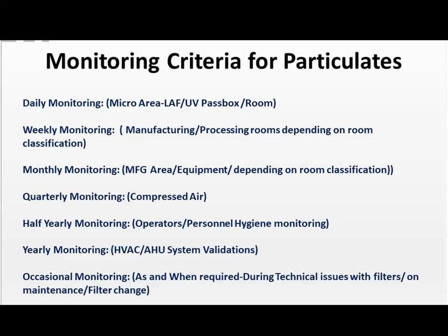We want to be sure that we're doing personnel monitoring on operators on a semi-annual basis, so twice a year. And this is for operators and personnel that are not entering into aseptic suites. This is for non-sterile manufacturing. We need to have our HEPA filters or our HVAC systems and our air handling units revalidated on a yearly basis. So we need to monitor those and have them revalidated or recertified every year.